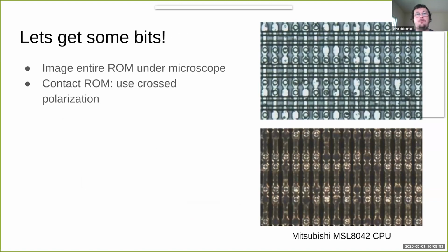Okay, so you have this chip now. You understand basically what the boot ROM is. You need to be able to do at least some basic imaging to get good enough images to extract the data. And my first piece of advice is, even if you want to image the entire chip, I highly recommend that you do a dedicated imaging to just the mask ROM.